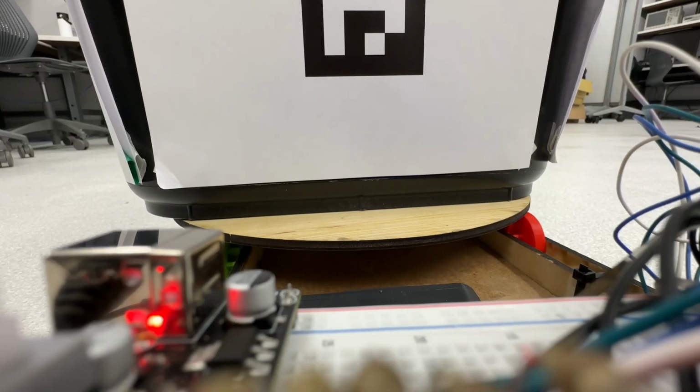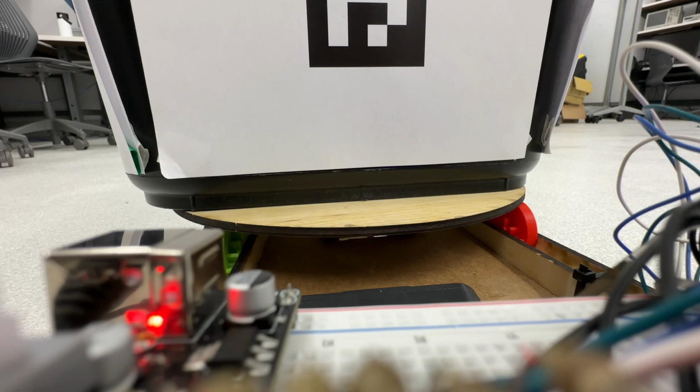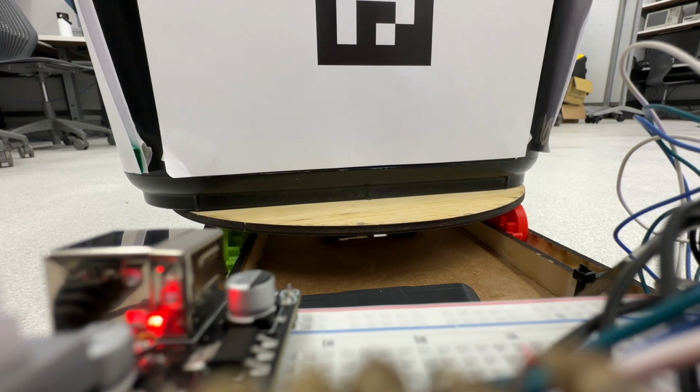During testing, the robot demonstrated a battery life of up to 4 hours with constant movement and has proven to be quite accurate in its sensing capabilities, with a 99.6% lidar accuracy and a 92.3% camera accuracy. Although we did not meet our goal of being able to lift a 10-pound load, we were able to lift up to 5 pounds, which is sufficient for most office waste. Given a higher voltage battery, we believe we could meet the 10-pound goal.